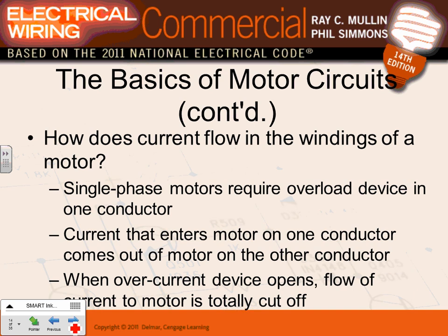Okay, how does current flow in the winding of a motor? Single phase motors. This is just a couple of things to justify the overload, guys. If you have a single phase motor, you have to have an overload in the phase. If you have a 3-phase motor, you have to have an overload in every phase, right? I'll show you a couple of pictures.